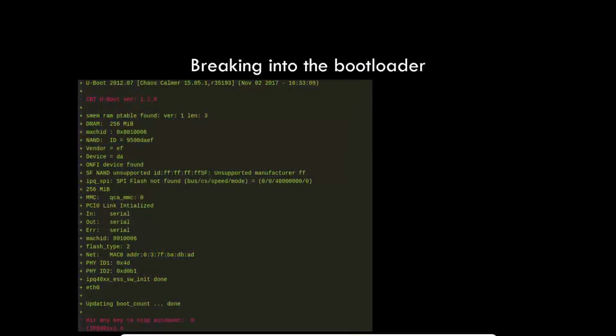So, breaking to the bootloader, can you actually stop into this process and try to see something or explore a bit of the attack surface? It's actually pretty simple, meaning that you see that it's U-boot on the screen already. You see the U-boot with the string boot version, and just press any key while the boot counter is going to 0. There is a short time frame, which may be disabled in some cases, that basically allows you to enter into U-boot. Again, nothing really special here.